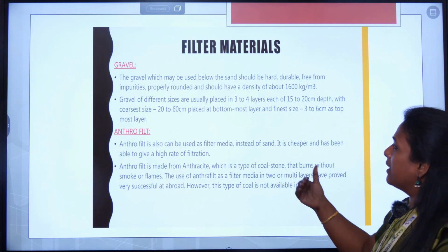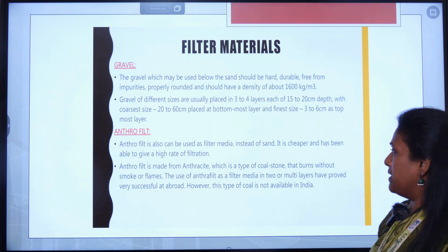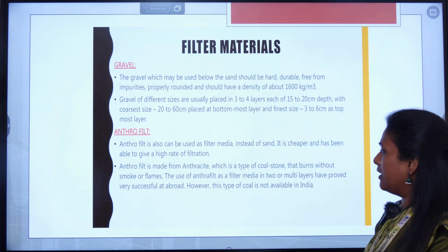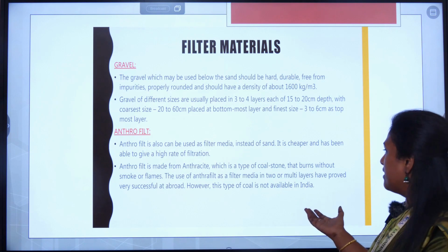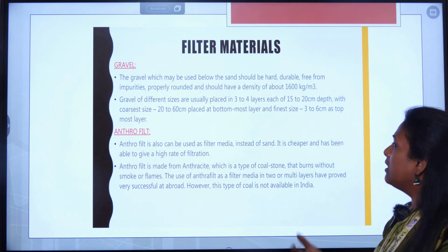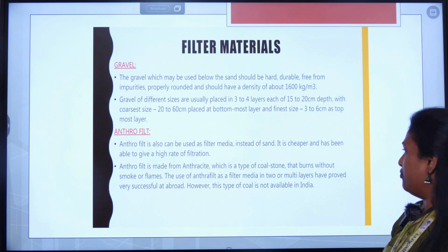Apart from that, we can also use anthrafilt, which is another medium. Instead of sand we can use anthrafilt, which is made from anthracite, a coal-like stone. It is not generally adopted in India, but abroad, where sand is not available, they use this other filter material called anthrafilt.